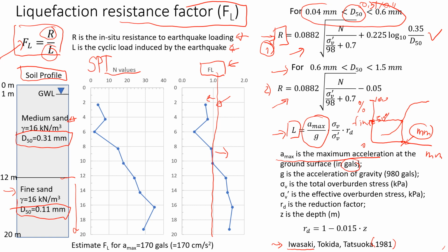So you can see, for example, that they will say maximum acceleration will be, I don't know, 0.18 g or 0.32 g, right? So they don't use gals, but if for some reason you see it here, you need to change g, which is acceleration of gravity, to this value of 980 gals. I will show later. We're going to look at this example.